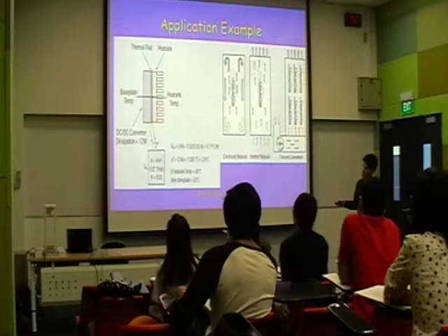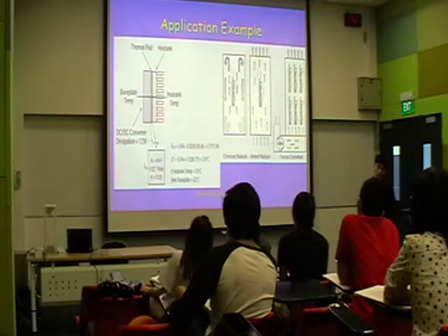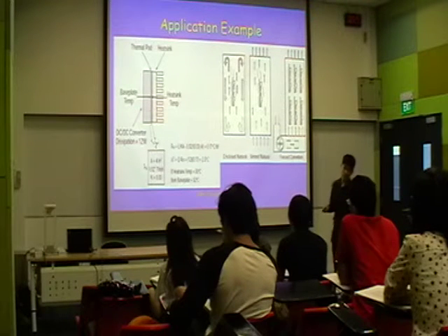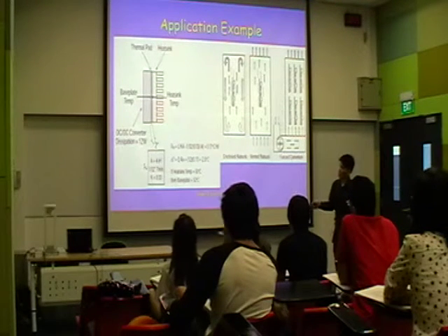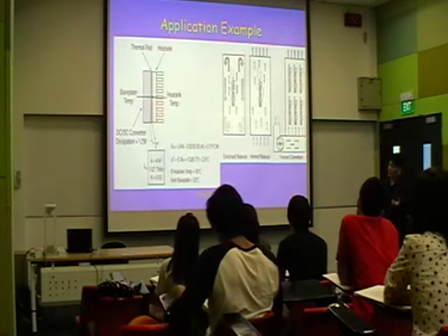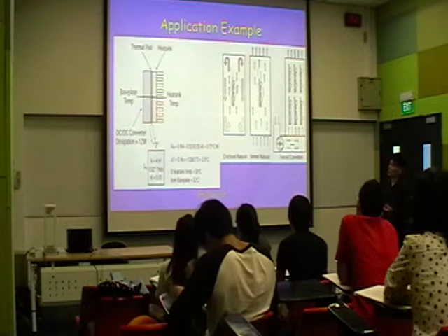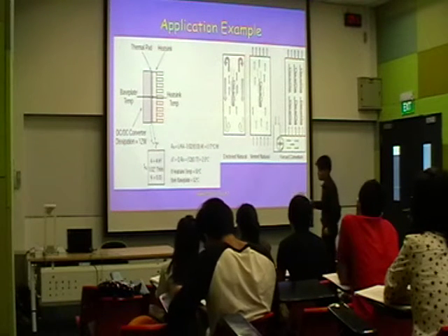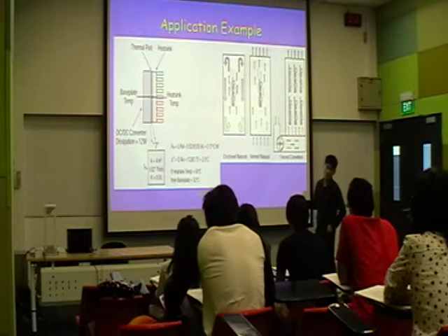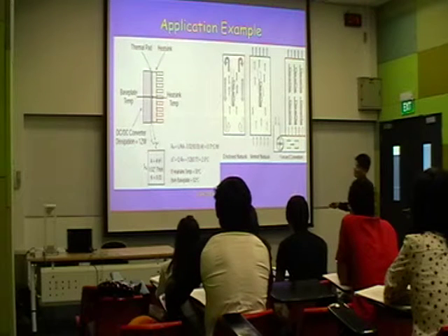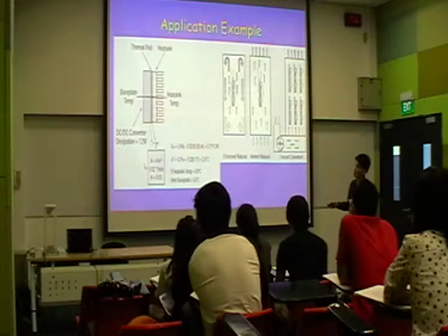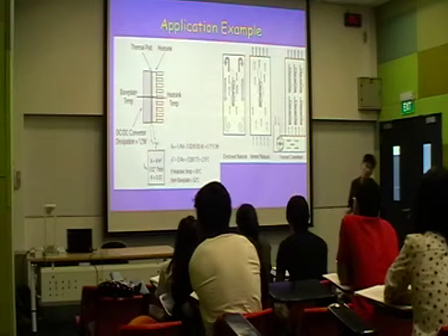For this case, it can be a DC-DC converter, or an inverter as well. So this guy here will give you 12 volts, the heat dissipation. All right. So to determine the change in temperature that this heat sink will give to this system, we basically use some formulas. It's the same as what you see, but in different symbols. The delta T is just like delta theta, and will be equal to Q, the heat power loss, times the total resistance R.